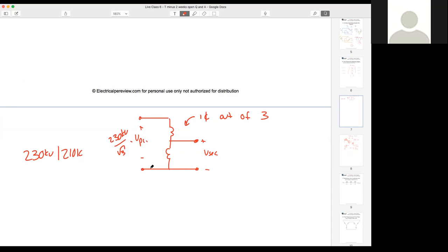I think there's even a sample exam where it gives the 3-phase bus ratings or transmission line ratings on both sides, but it gives you the line voltages. So it's a bit misleading, because they leave it up to you to realize, hey, even though they're giving me the 3-phase line voltage of the transmission line or the bus, and they're showing it directly underneath a single-phase auto transformer, which is kind of tricky, I know that the voltage across my auto transformer is actually my phase voltage. So we're going to see where that comes from.